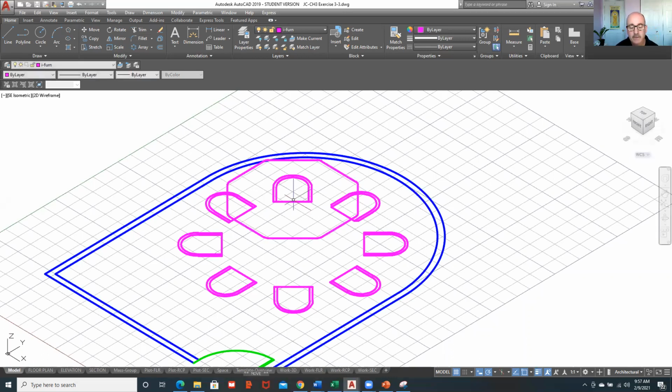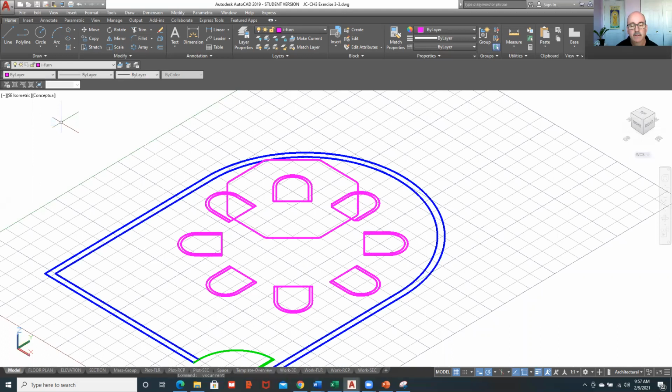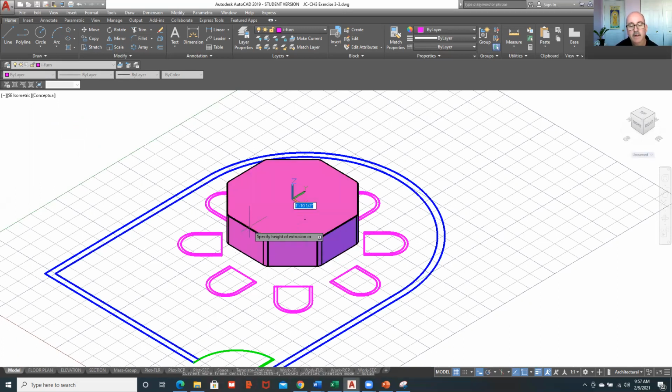And then as we start to work with it, I can do things like extruding it. Let's do that in a very visual mode so I can see it. E-X-T-R-U-D-E, extrude. And I could take that table, extrude it. And then I could say, well, let's just go 2 inches, make it a big, thick table. And so we can kind of work with polylines in that manner.